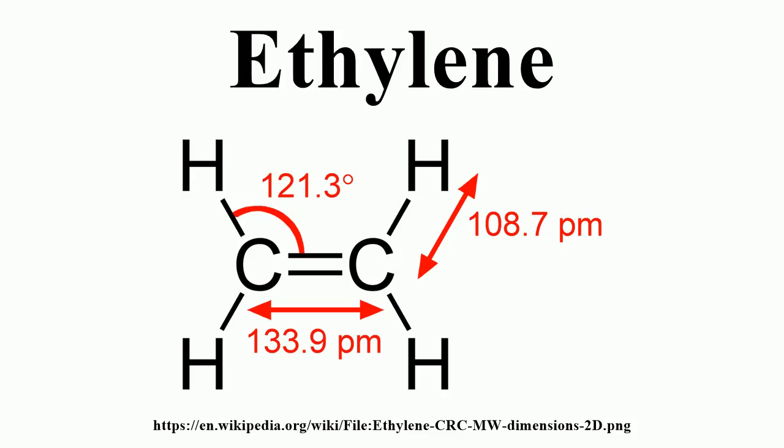All of the cold cracked gas stream goes to the demethanizer tower. The overhead stream from the demethanizer tower consists of all the hydrogen and methane that was in the cracked gas stream. Cryogenically treating this overhead stream separates hydrogen from methane. Methane recovery is critical to the economical operation of an ethylene plant. The bottom stream from the demethanizer tower goes to the deethanizer tower. The overhead stream from the deethanizer tower consists of all the C2s that were in the cracked gas stream.